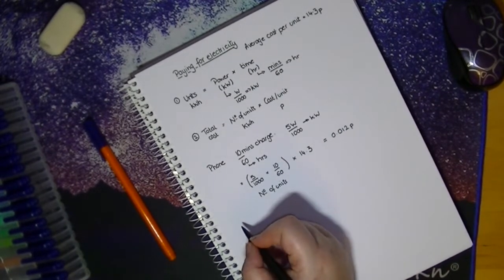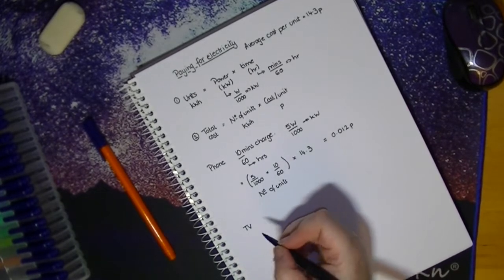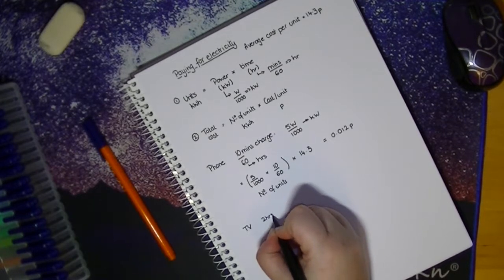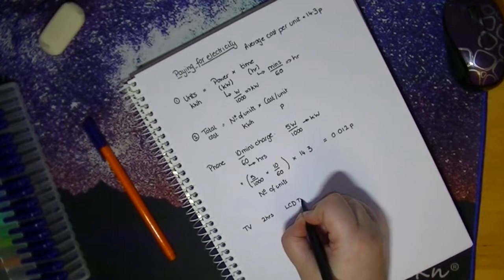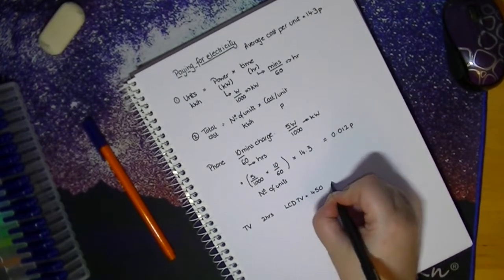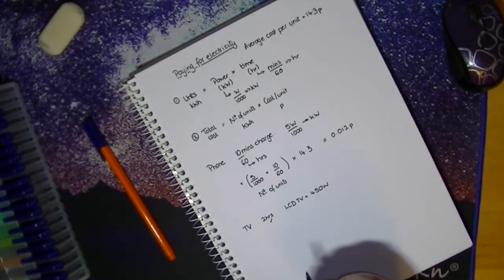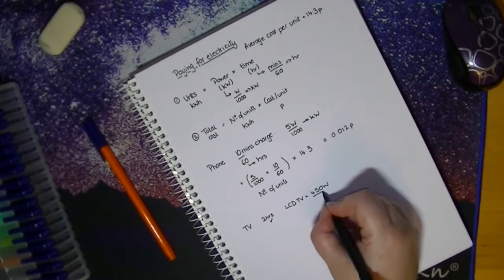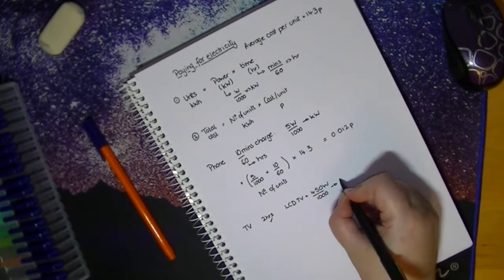Okay, then you know what? It's time to relax. I'm going to go and watch some TV. And there are 2 programs I really want to watch. So it's 2 hours. An average LCD TV, well, that draws 450 watts. So my time in hours, brilliant. I don't have to do anything to that. My power is in watts, however, rather than kilowatts. So I'm going to divide by 1,000 to get my power in kilowatts.